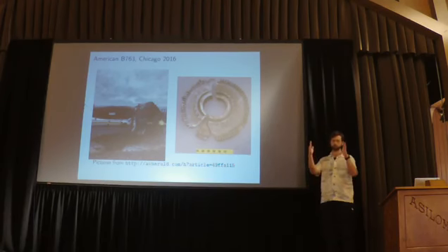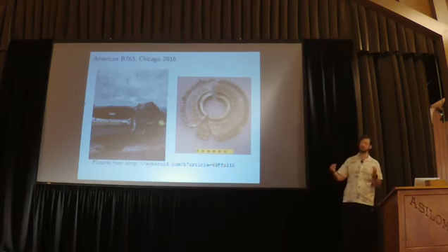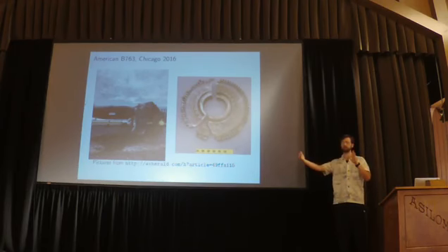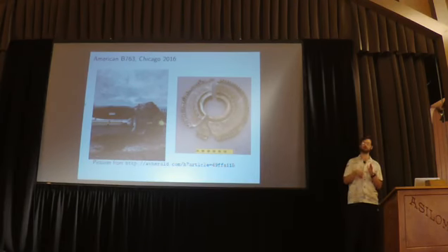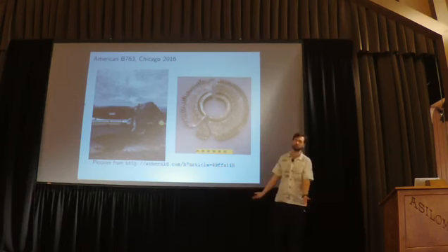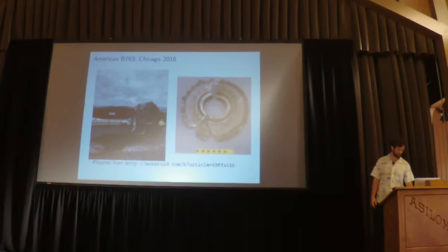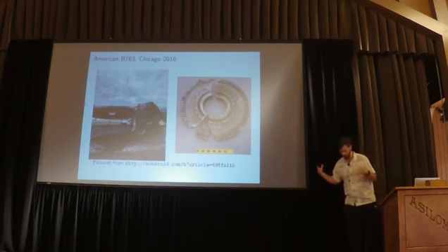If you have a spring and you displace that spring away from its resting length, it will try to pull itself back together. And the magnitude of the force that it produces is linearly proportional to that displacement. The coefficient of proportionality is its elastic constant. And basically, we try to estimate these elastic constants for materials more complicated than springs. They're still linear materials, they're just more complicated. And I'll explain more about that in a second. So I wonder what the next slide is. Oh, yeah, so how are we actually going to get those elastic constants?